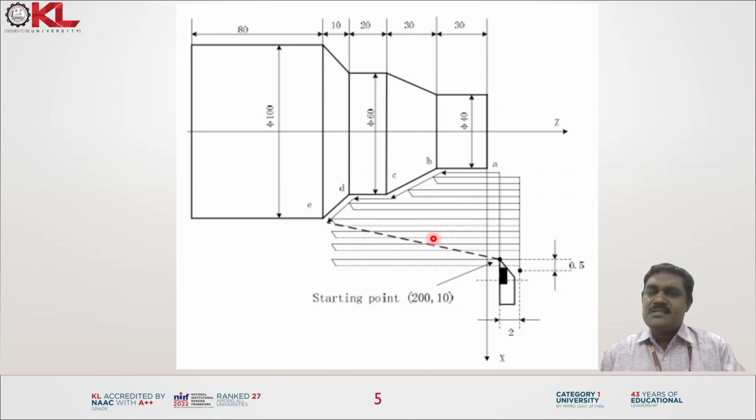All these operations can be taken by the same cycle. That is why we mention the starting block number and ending block number. Between them, this process goes on continuously till the end point. So the entire material is removed. Only the small amount of material left over is removed in the finishing cycle. This is the process actually taking place in the multiple turning cycle.